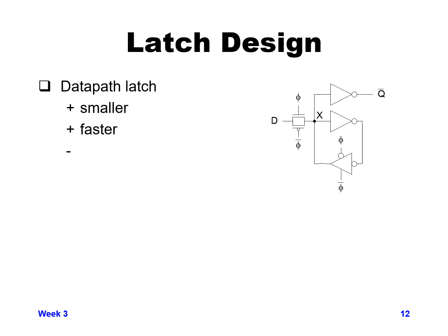And it's going to be faster since it only has to go through a single pass gate and inversion, so it can be not quite twice as fast, or half as slow, half as fast. It'll be faster than the previous design because you go through less propagation delay, and the downside is you no longer have a buffer on your input, and so that could cause problems depending on the drive strength.